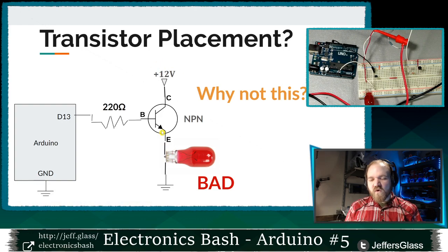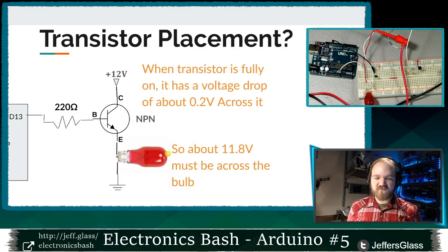Well, when we want this light bulb to turn on, what do we mean by turning the light bulb on? Well, we want to put a bunch of voltage across it. It's a 12-volt light bulb. I want to have 12 volts or so present on one of its wires and 0 volts or so present on the other one. So for this light bulb to be on, as much as we want it to be, I need to have 12 volts or so across this light bulb.